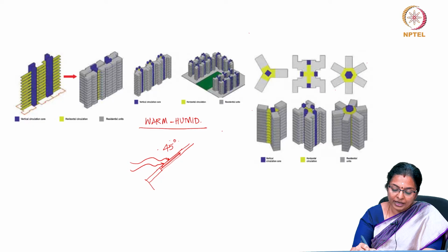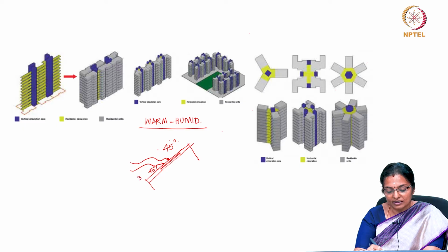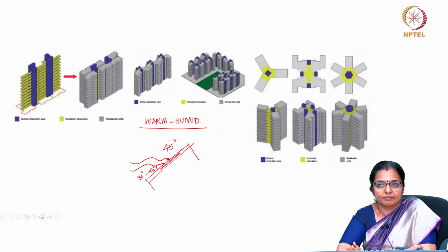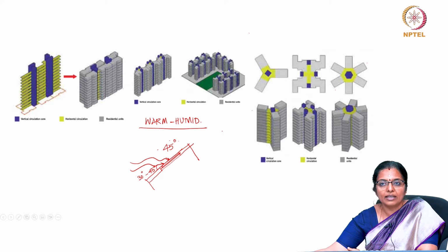So, you orient the room at a 30 to 45 degrees angle if you want to bank on catching the prevailing breeze.